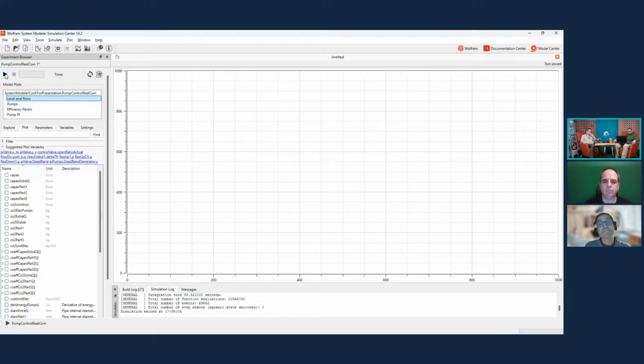Right. We have a question from Martin. What variables did you use for the interface in your library, like in the connectors? So at the interface, in our library, we call it the head library, we use total head in meters, which is kind of pressure, but expressed in meters of water column.